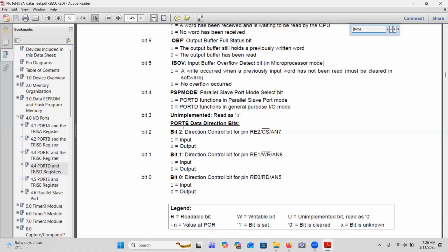Yes, sir. So first we will create a toggling program and execute it in the hardware, so that it toggles the LED that we have on the motherboard. Why did I choose port D? Because in my motherboard they have connected the LED only to port D. Otherwise we might have done it with port A. So let us start the program.